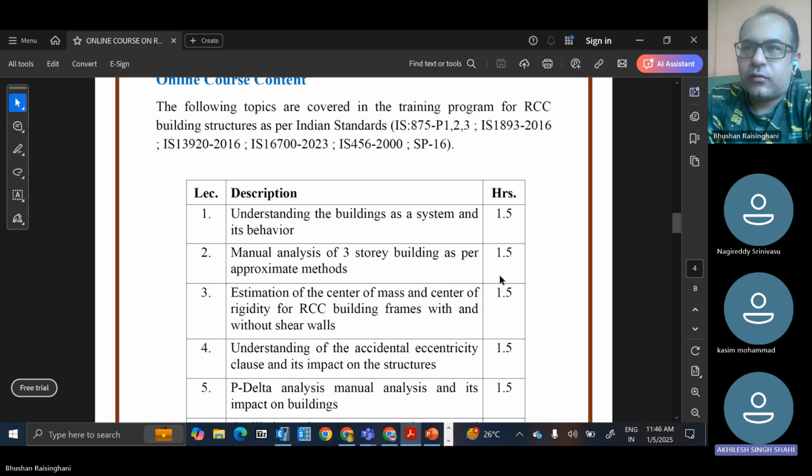Yes, sir. So that is the one part that we are actually depending more on the software, that now this is the practical case, but we don't know how to evaluate it. So whatever software is giving, we are going ahead with the capacity of that column, and what assumptions we had taken, or why the SP16 is not having four-side distribution. So nobody is also questioning that. Nobody is asking the BIS committee to improve the SP16 code and include four-side distribution. How software is able to do that, and we are not able to do that.